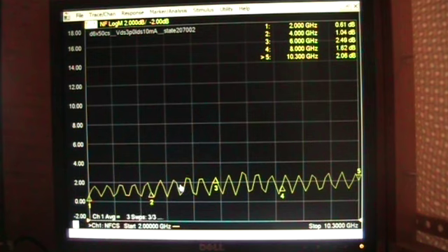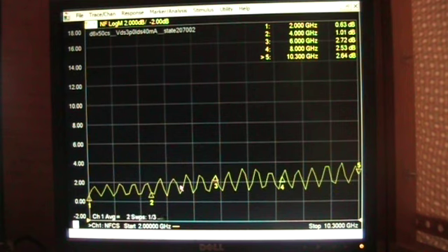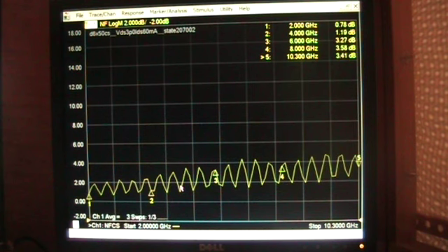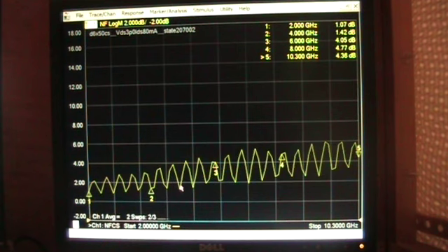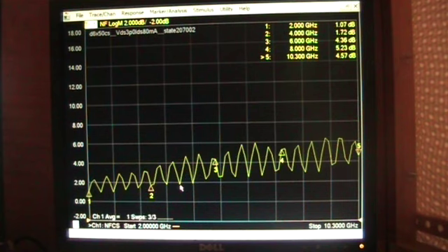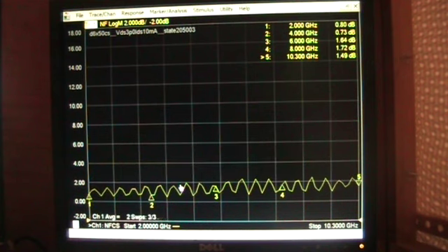The tuner is actually moving the carriage from right to left in one pass for this 2 to 13 gigahertz sweep, and then varying the gamma, the z-axis motor, if you will, as is required as it works its way across. This also is optimized for speed. So in this particular case, to run from 2 to 10 gigahertz would probably be 10 to 15 minutes worth of measurement time for this particular sweep.